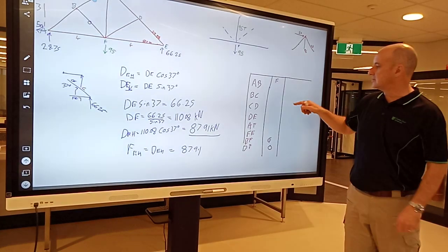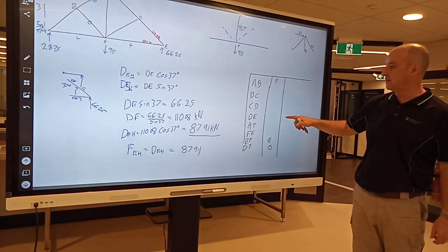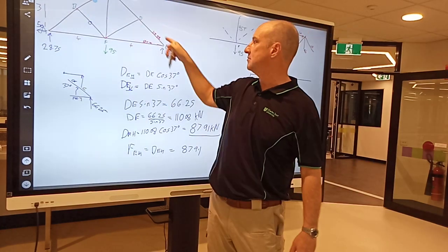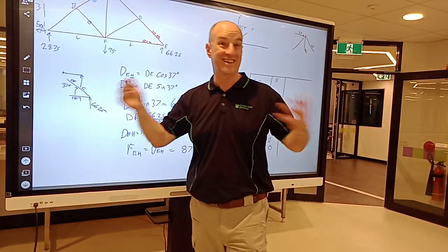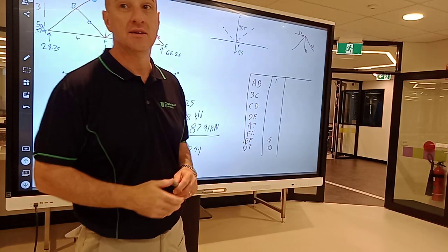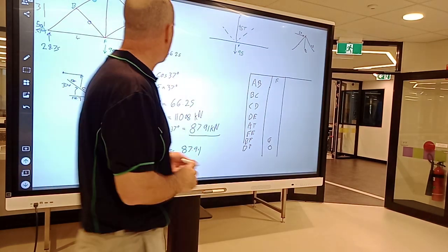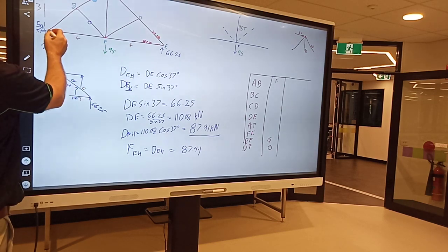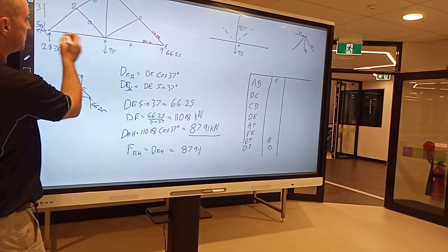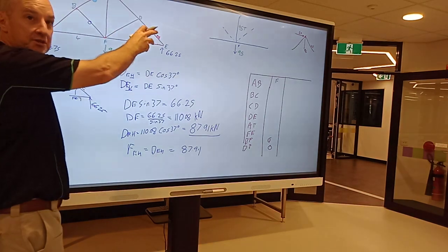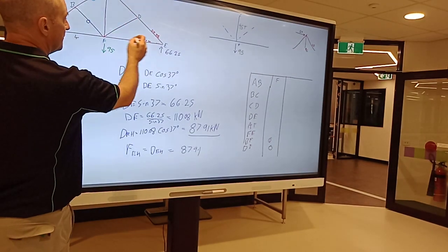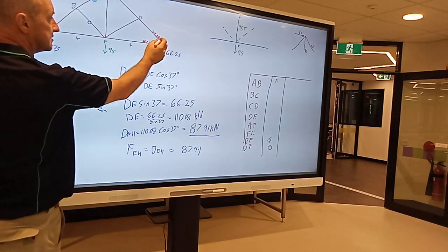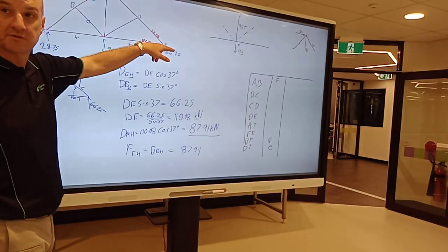And when you say here that DE, for example, gets longer, make sure that when you draw it, if you give me coordinates of that, that it actually is longer. Okay. When you come to do it with the geometry method, one way you can do it is assume that's horizontal and then work out what this triangle is, and then rotate the whole thing down, because that point obviously is fixed in the horizontal direction.